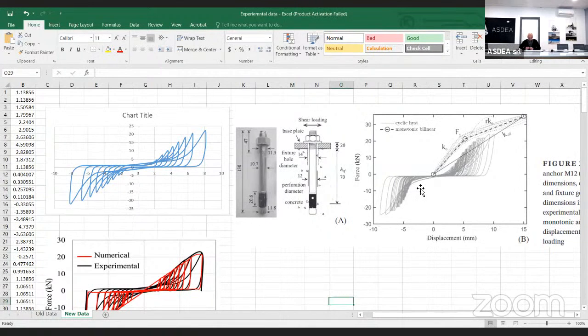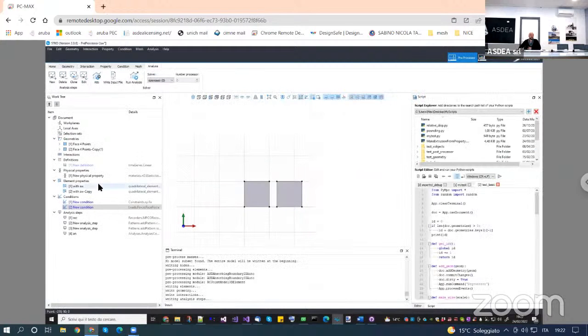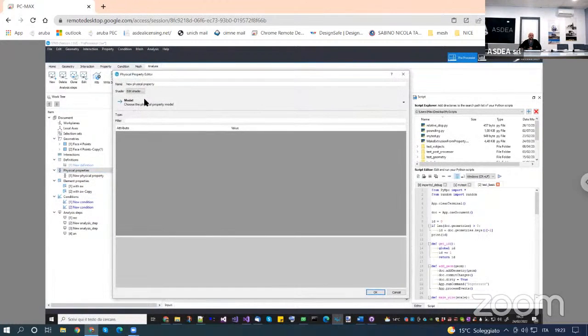Okay. Yeah, so in general for testing, I mean, I'm not a specialist of this kind of material, but I think there is something like this in OpenSees already. Let me share my screen. Okay. So whenever you want to test something in STKO, first of all, you need to understand if there are material models in OpenSees that resemble what you want to do, okay? And then you can use the material tester.